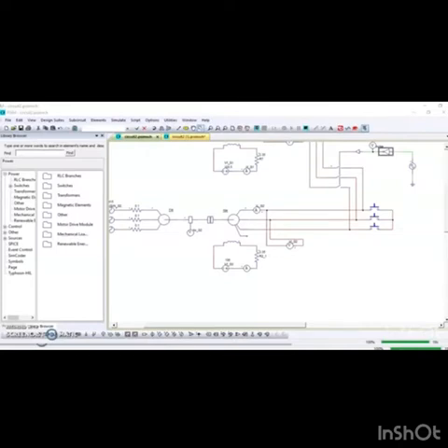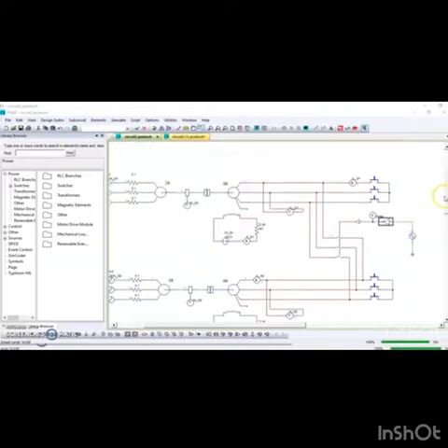For question 3, to design the parallel connection of three-phase synchronous generator, they have conditions. The RMS value for the line must be equal or the same value. The two generators must be in the same sequence, and the two generators must be in the same phase, and lastly, the frequency of the new generator must be higher than the frequency of the running system.